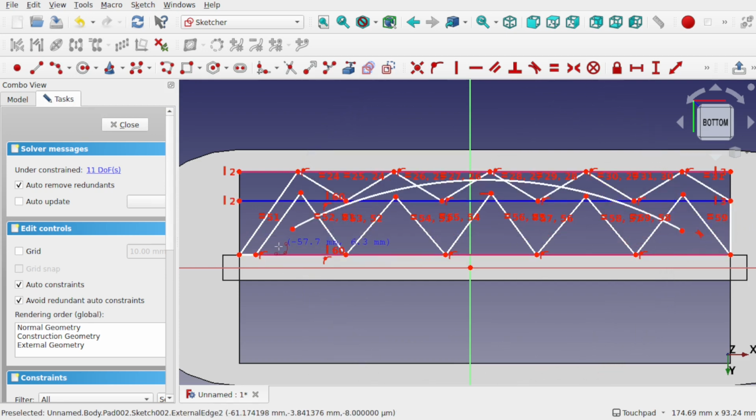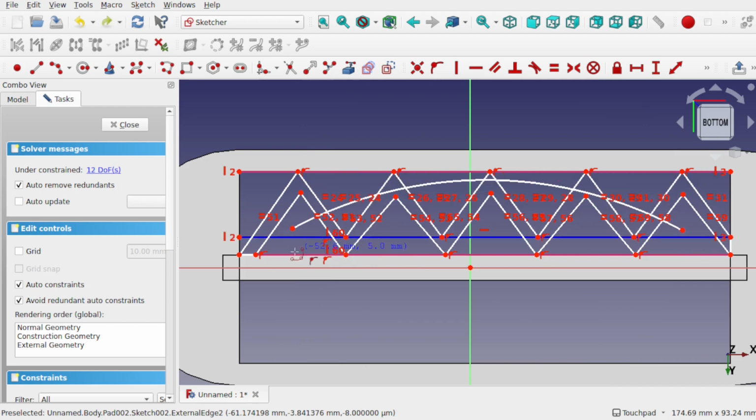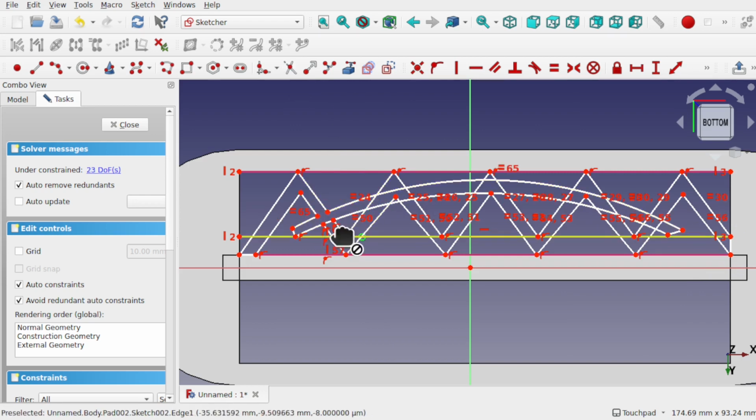We have to create a second skin inside, and then go through and create the endpoints like so. So it's taking a long time, and then we still got to remove all this inside here with the trim tool, and remove this in here, and remove this, and by the time we've finished, it's taken quite a lot of time.